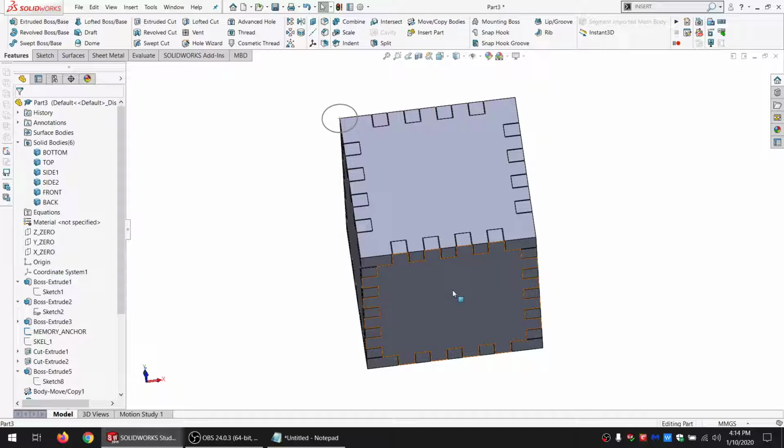The people that make SolidWorks will tell you you don't need to worry about kerf. Just send it to manufacturing, and their machine will figure it out for you because they all have this. Well, they don't all have kerf offset, and the ones that do don't always work so well. So I like to do kerf from within SolidWorks. Just send it to the machine and say, follow this line, don't worry about kerf, and it does it right.